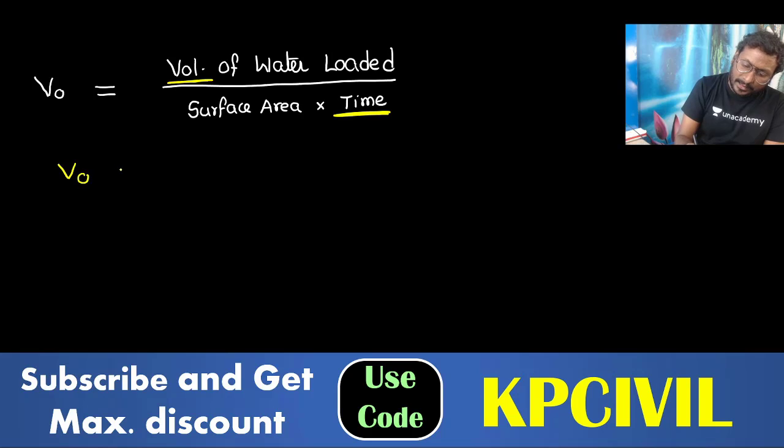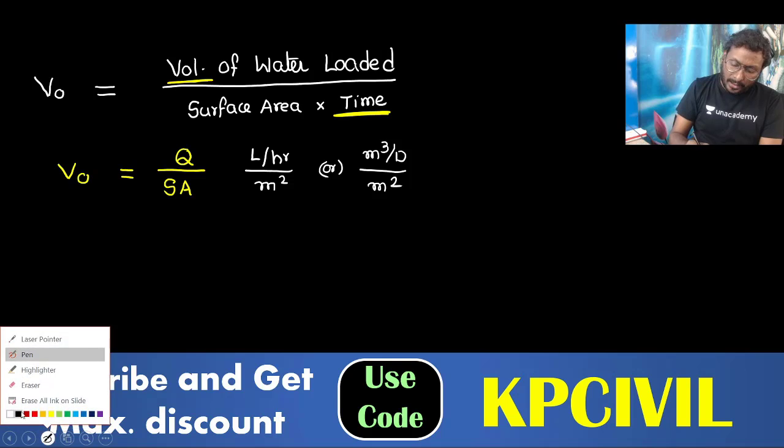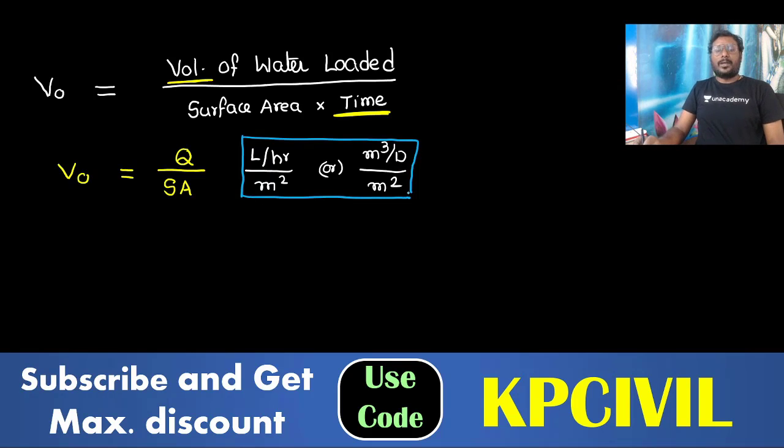So V0 is equal to discharge by surface area. Which units does it represent? You may take discharge in liter per hour and surface area in meter square, or discharge in meter cube per day and surface area in meter square. So V0 is expressed in liter per hour per meter square or meter cube per day per meter square. V0 is equal to Q by SA.